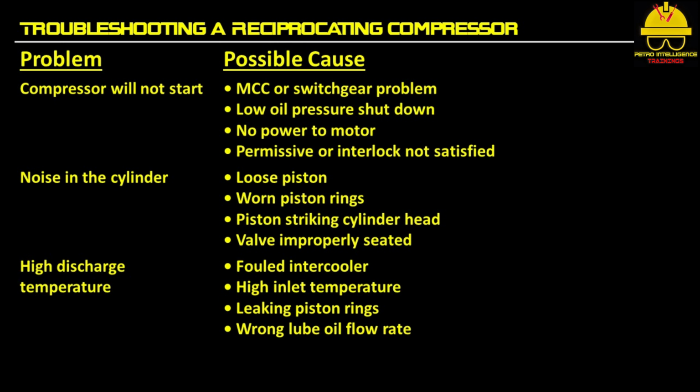If there is a noise in the cylinder, there might be loose piston, worn piston rings, piston striking cylinder head, or valve improperly seated. If there is high discharge temperature, there might be fouled intercooler, high inlet temperature, leaking piston rings, or wrong lube oil flow rate.